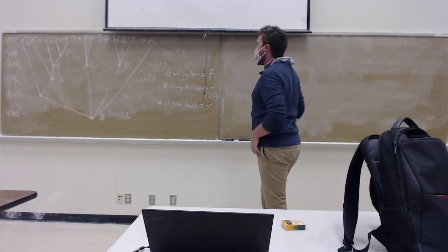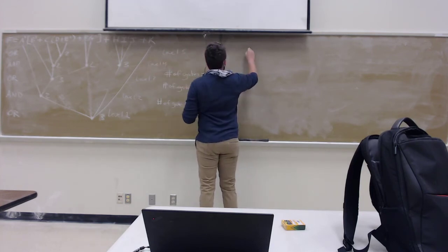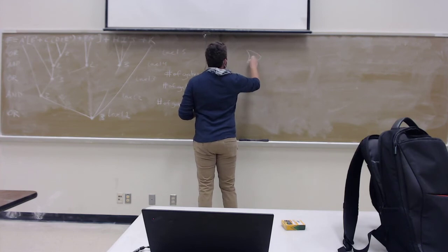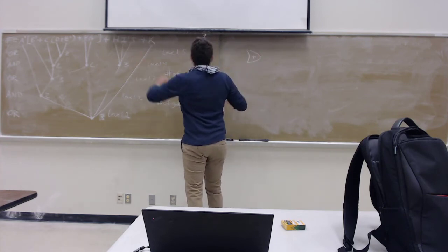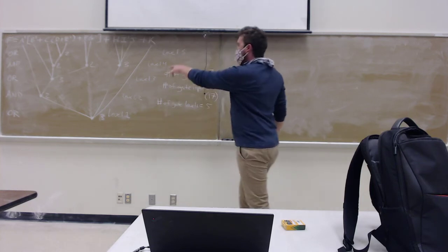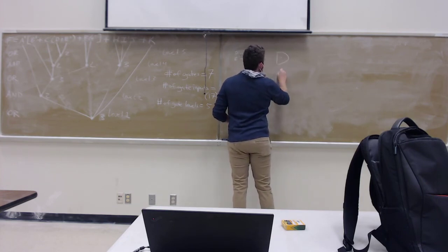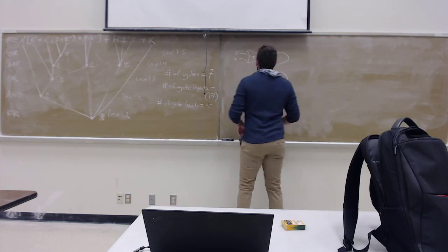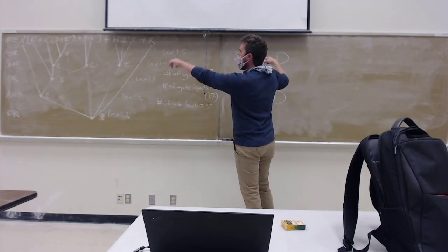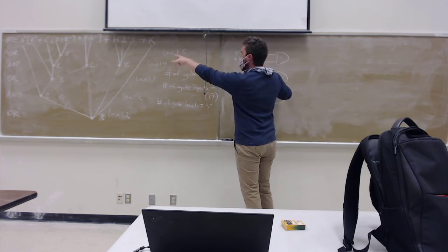All right, let's go ahead and draw the circuit here. So now we've got a framework. We can start with, back to back here, level 5, and then an OR gate, which had C or D or E prime. Then we had a level that consisted of 3 AND gates. The first one was the output of our OR gate and C. The second one was F and G prime.